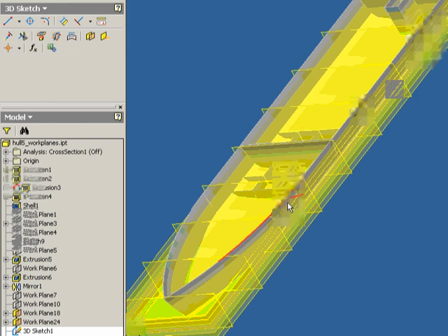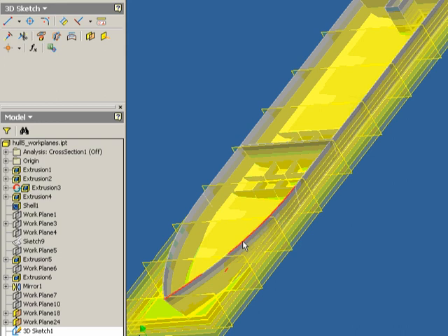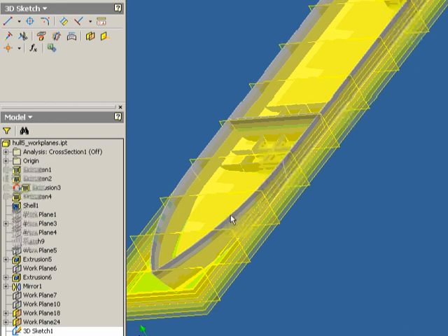Now, we had a lot of trouble calculating the half-breadth distances for curved planes. We had a lot of trouble with this, and I'm going to show you how we got around it and managed to figure it out. Basically, for the half-breadth distance, we've got to make a mark at the 3D intersection between these station line planes, the waterline planes, and the hull of the boat. Okay, we did pretty well on flat surfaces, but again, curved surfaces were a pain.